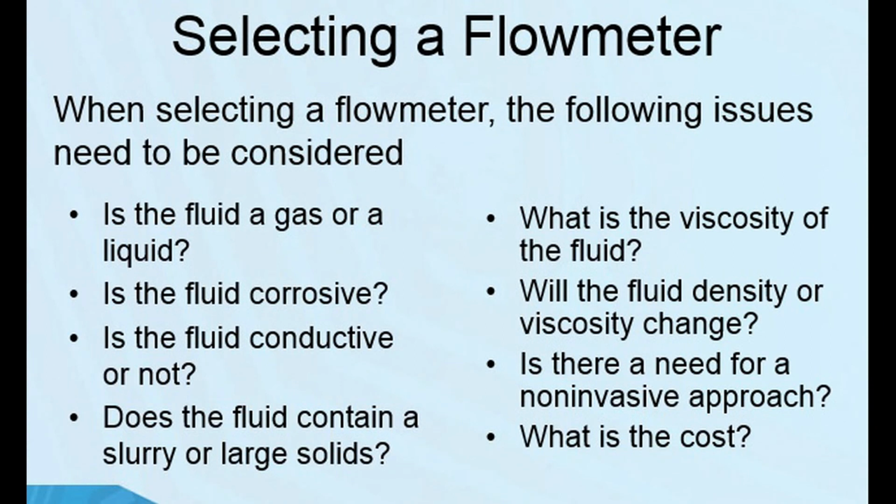Here's a table for selecting flow meters. And as we said before, the first consideration is: is it clean? Is it dirty? Is it explosive, corrosive? Does it conduct or not conduct? And these will help you select a flow meter for different applications.